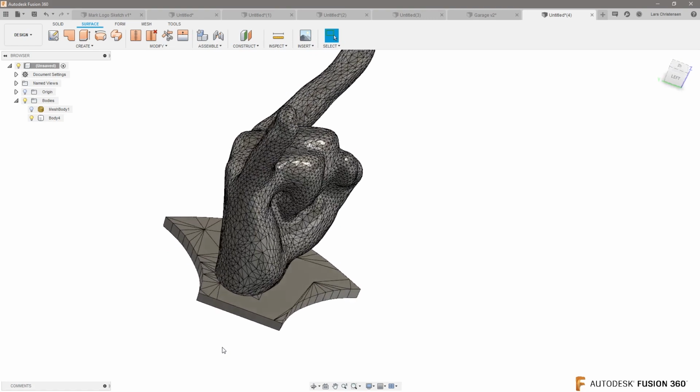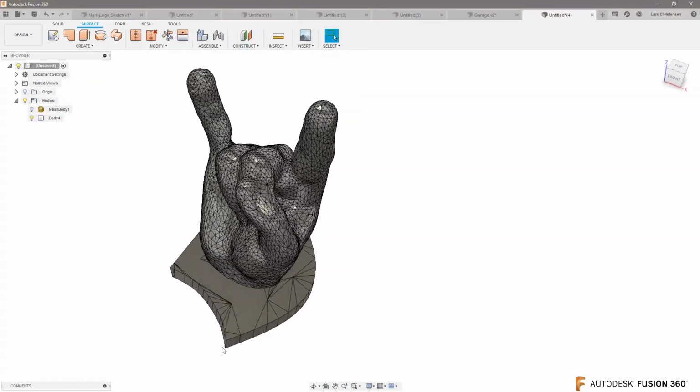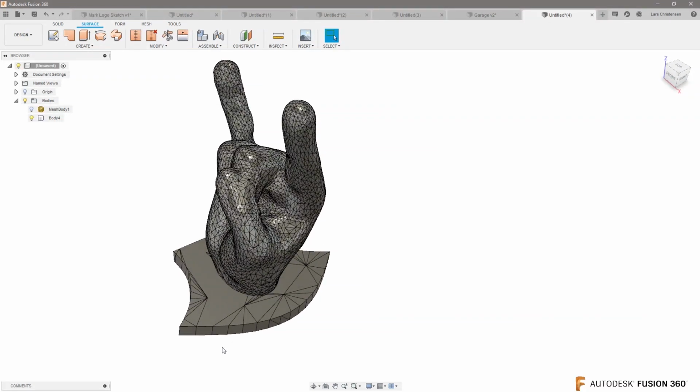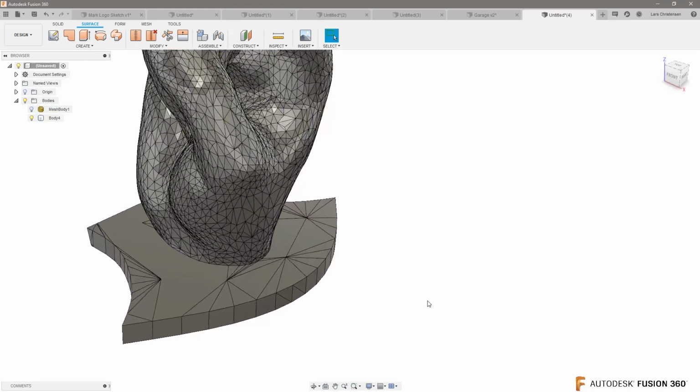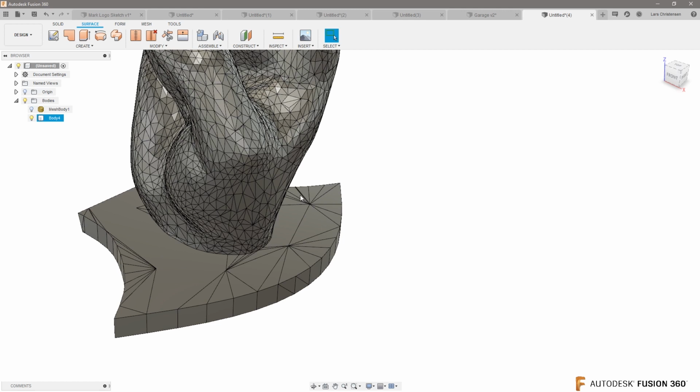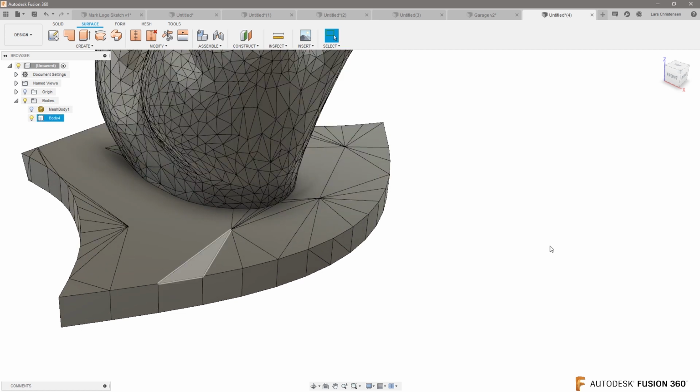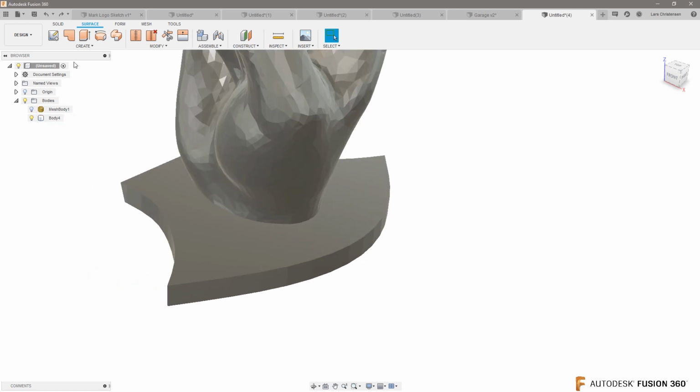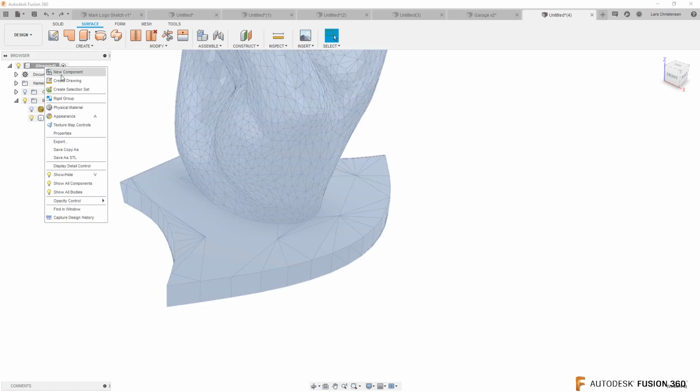Now, I did all this work, Ryan, just to get to the point of showing you a couple of tricks to do this. So, first of all, know that if those 100,000 facets you have are big facets, like on this flat plateau here, you can actually select that area, hit delete on your keyboard, and Fusion is going to try, whoops, you might have to go back in and turn your feature tree on.